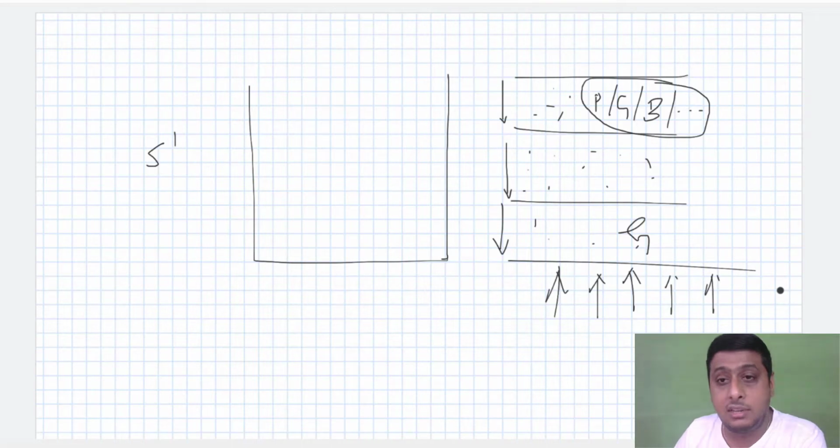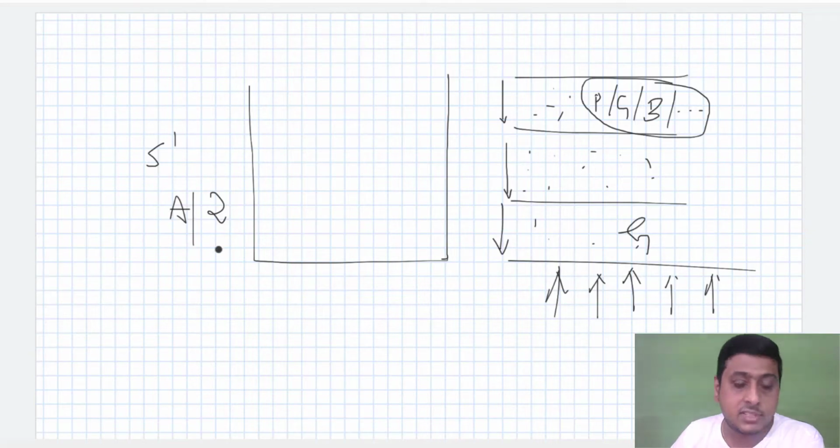So during soil excavation, we should not just stand at the corner of the site operating the mobile and passing our time. It's not like that. We should actually go and inspect each and every pit, see how the layer is changing, whether there is any filled up soil, and how it has to be tackled. All those things have to be seen and noted, keeping the grid lines. When we do the marking, we will have a grid line for every footing. For example, in grid A2, what observations did we make.